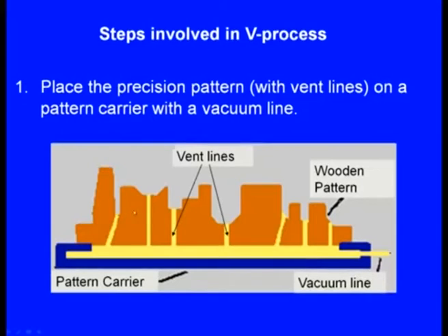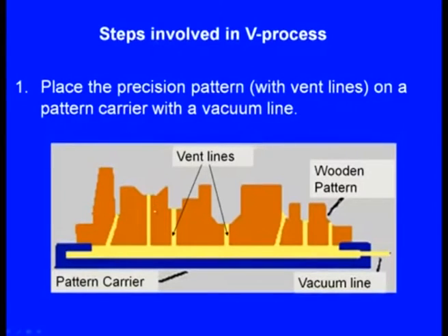Now, why these vent lines? This wooden pattern will be covered with the strong polymer film, then the vacuum will be applied, and as the vacuum is applied, the polymer film will be sucked through these vent holes. So, that is the purpose of these vent lines.